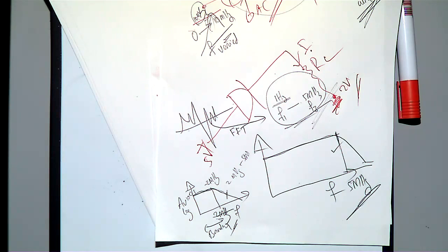Now we are going to look at the frequency response. This is a simple low pass filter. A simple low pass filter means you have a voltage signal, then a resistance, then a capacitor connected between this resistance and ground. When you have different frequencies here with the same amplitude, you can find out the gain.